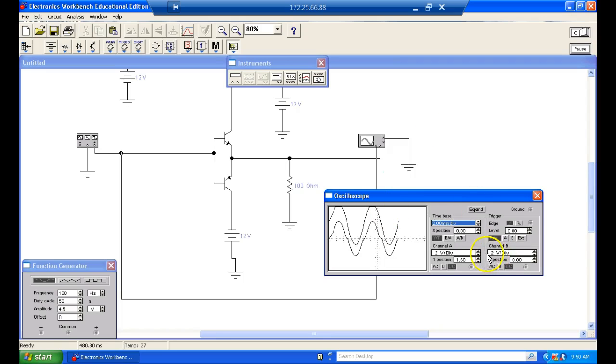We can come over here and put them on top of each other, and then come down here and bring this one down. Yeah, so it's slightly smaller, but it's got that little, we call it crossover distortion. It's got the crossover distortion. Now, why is it slightly lower?